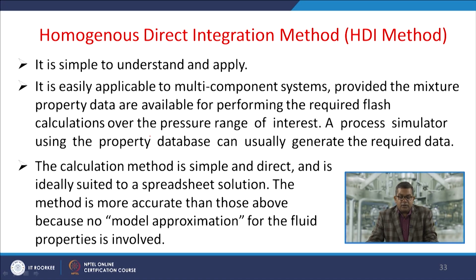So it is simple to understand and apply, obviously, which is evident from the previous calculation. Now it is easily applicable to multi-component system, provided the mixture property data are available for performing the required flash calculation over the pressure range of interest. Now a process simulator using the property database can usually generate the required data. The calculation method usually is simple and direct and is ideally suited to the spreadsheet solution. So the method is more accurate than those above because no model approximation for the fluid property is involved.